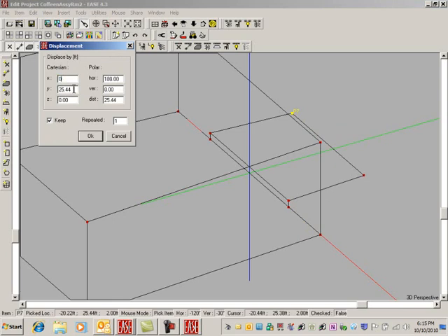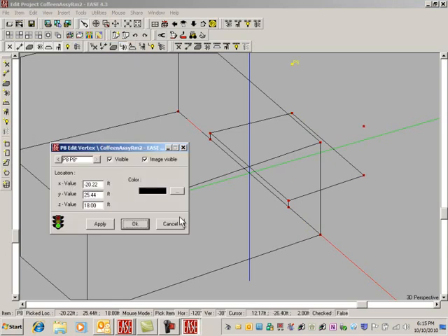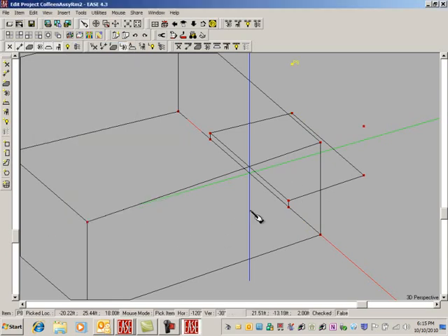And about minus 22 somewhere. I'm looking down at the bar at the bottom of the screen, there's minus 22.31, a little bit to the right of center. But I'd really like it to be 22. So if I select it and do an F4 would let me change it to minus 22 feet, even. Say, okay, there we go.